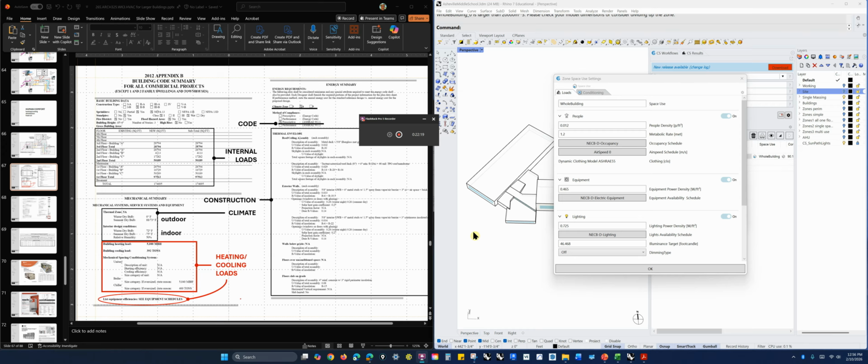So it's a way of, rather than having to specify all the equipment, you use these accepted standards for different situations. This is a pretty low power density. They're generalizing because you don't have any in stairs, and you're not going to have any in corridors. If this were an office, it would probably be 0.7. If it's an older building, it could be 1.5, and if it was a data center, it's going to be very high. But anyway, these are using energy. They're giving off heat also, and we have a schedule for these, or we could say all on.